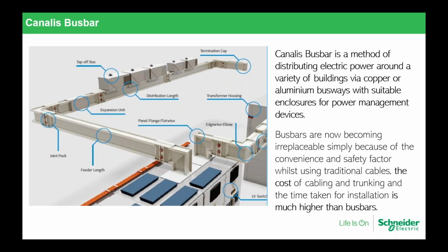We are saying that Busbars are now becoming quite irreplaceable simply because of the convenience and the safety factor, compared with traditional cables. The cost of cabling and trunking and the time taken for the installation is much higher than with the Busbar. And we need to take into account also the fact that with the Busbar we do a lot of tests in the factory.